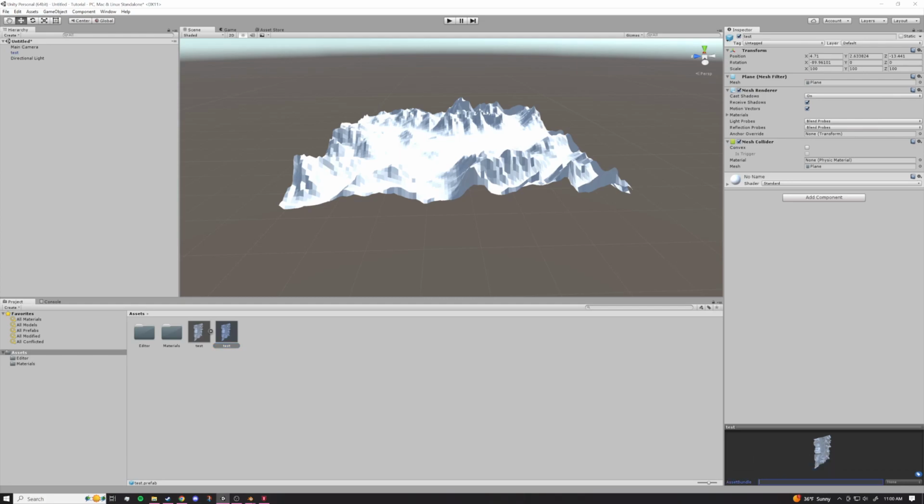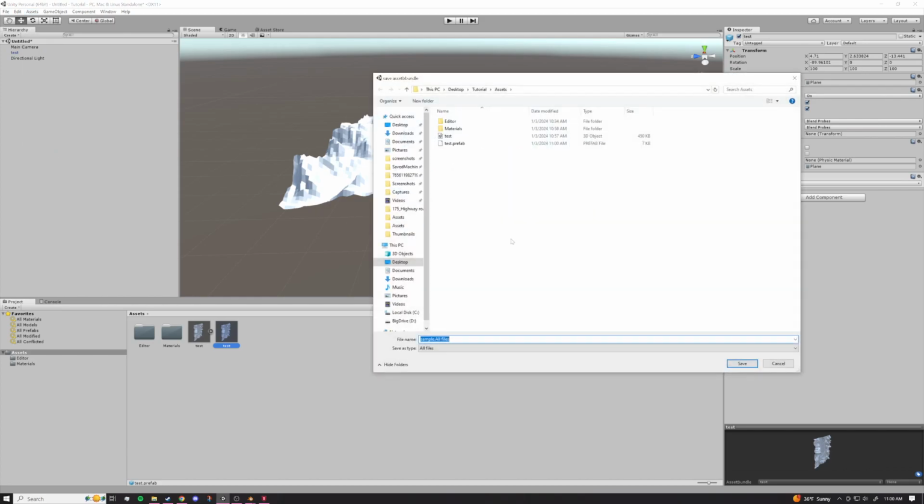You're going to create a new asset bundle. I'm just going to call it test. It doesn't matter what you call it. Its name is never going to be brought up again. You have to select the objects you would like to export. Go to Assets, Export Asset Bundle down here. Export Asset Bundle, Windows, Mac, Linux. I'm on a Windows machine, so I'm going to be making this for Windows. So I'm going to select Windows.